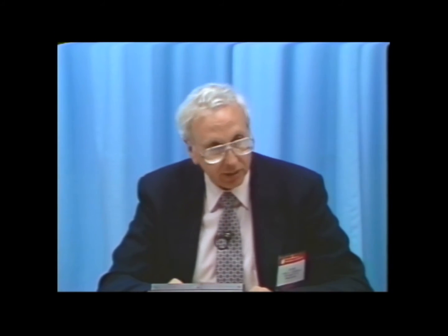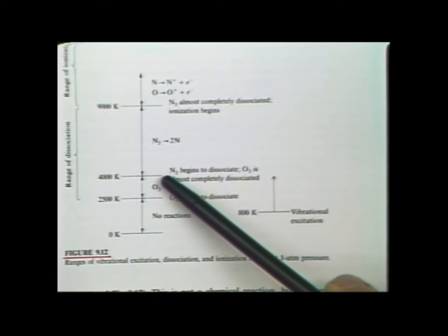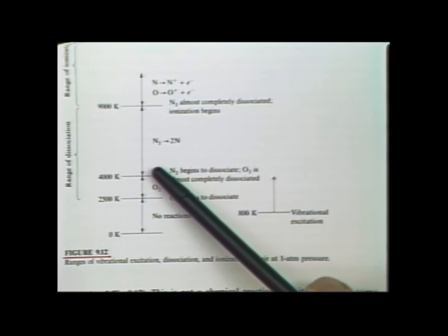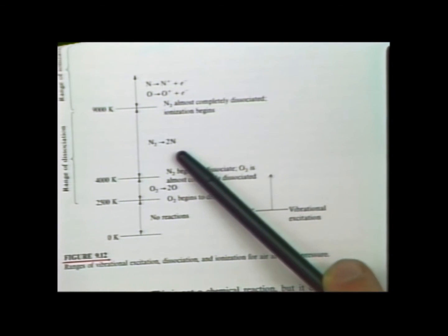They're real life. But what you're really dealing with here, when you get these chemical reactions, is a chemically reacting mixture of perfect gases. And in this range here, PV still equals RT, just R is a variable, because the molecular weight of the gas is a variable. So when you want to talk to your physical chemist about how to handle the chemically reacting flow over a hypersonic vehicle, where the temperatures might be 5,000 K and you're deep in this dissociation region, you run down the hall and say, man, I've got a problem.